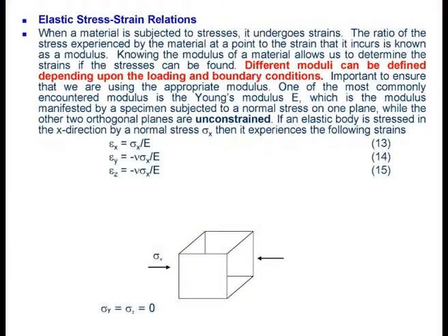If you say tension is positive, then very often you have to tag on a negative sign to all your numbers, and it becomes rather inconvenient. So people do it the more convenient way by taking the negative to be compression. Similarly, compressive strain is negative, and compressive stress is also negative.